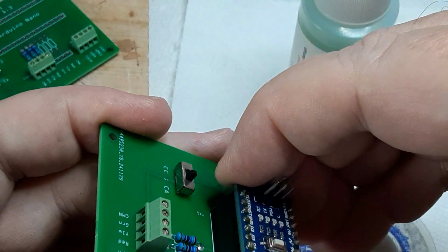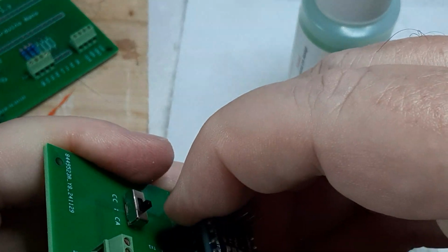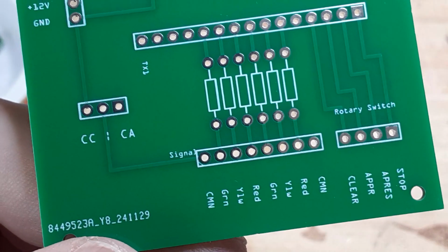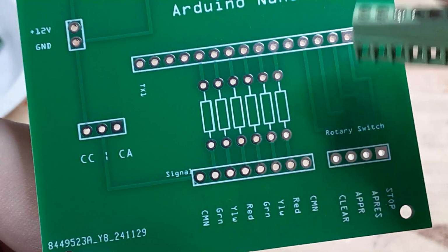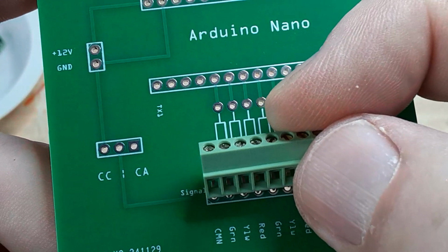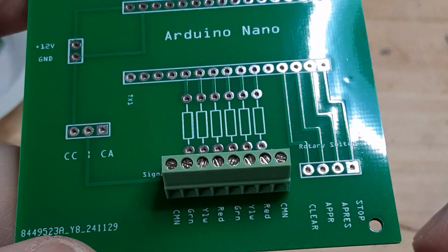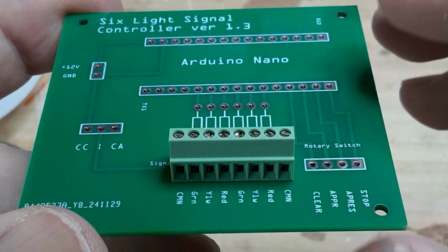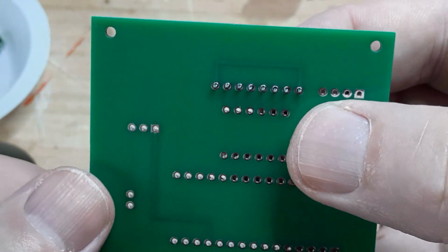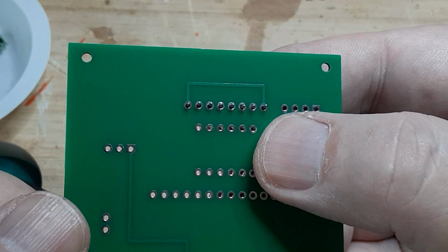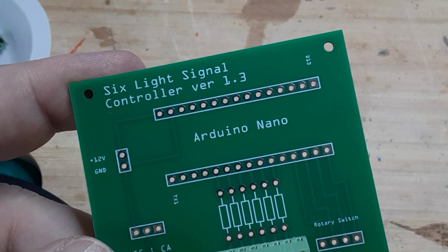Once the header blocks have been soldered in place, you can remove the Nano, for programming if you like, and reinstall it easily. You really need just 7 connections for a 6-light signal: a common, 2 green, 2 yellow, and 2 red connections. However, 7-pin screw terminals are hard to find, so I designed the circuit board to accept an 8-pin screw terminal. The 2 end connections are the grounds, and they are connected by the printed circuit. If you don't have any 8-pin screw terminals, you can use 2 4-pin terminals side by side, or even a 4-pin next to a 3-pin terminal.